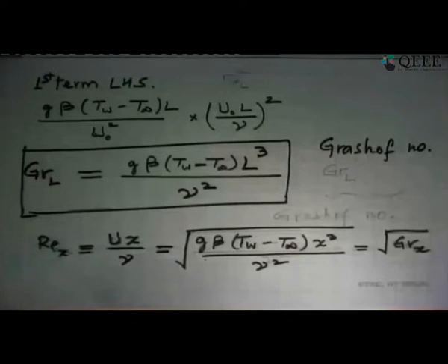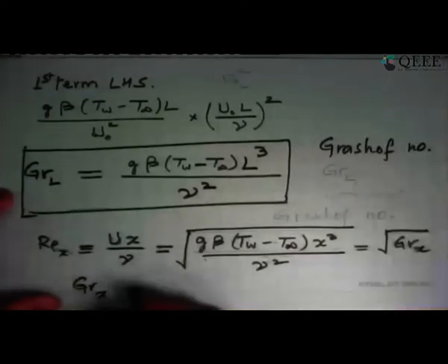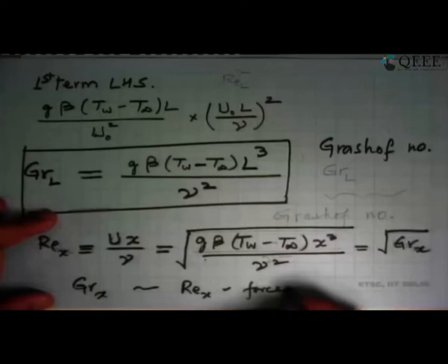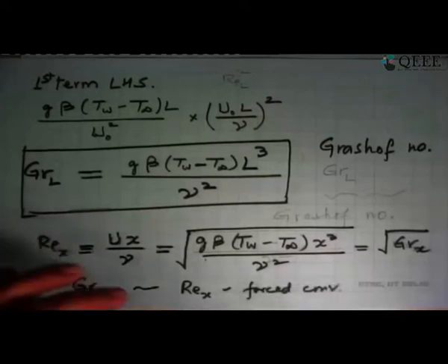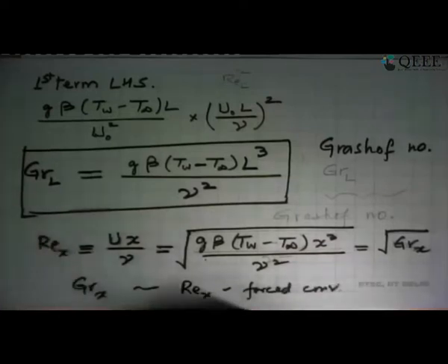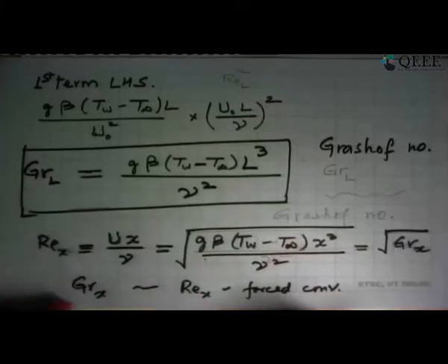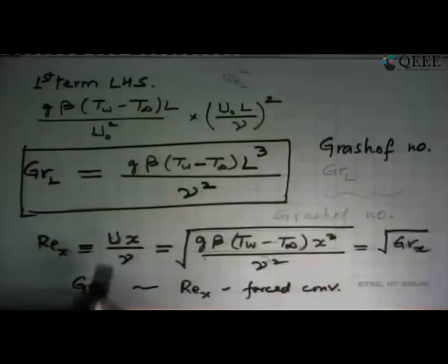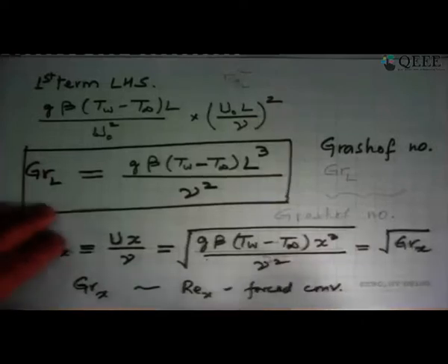So what that means is that the Grashof number plays something of the same role, the same importance that Reynolds number had in forced convection. And consistent with all these types of flows is that the non-dimensional parameter in that equation was the Reynolds number, but now with buoyancy, it is a modified Reynolds number which includes a temperature difference term inside it. That is what we have here.